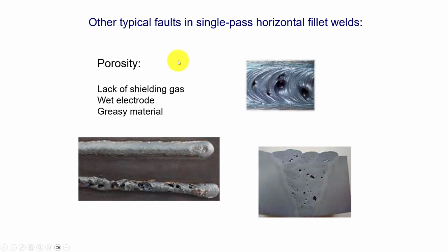Inspecting the welds, we want to do a quick visual for porosity in the weld. We want to think, did we have shielding gas? Here's a nice weld. Here's a weld without shielding gas, and these little porosities that get in the weld are going to cause defects and make the weld break. Now this is a multi-pass weld, and we had issues with gassing at each pass here.